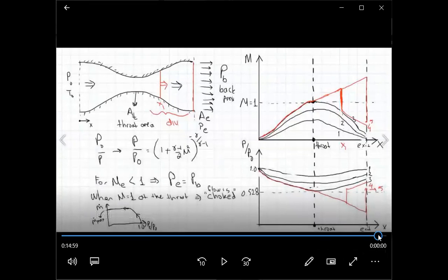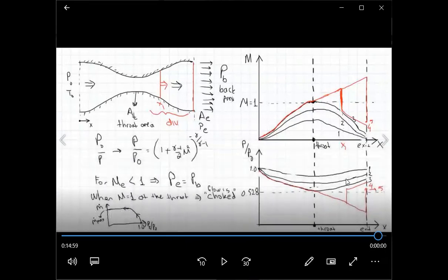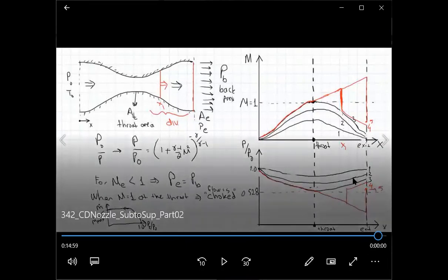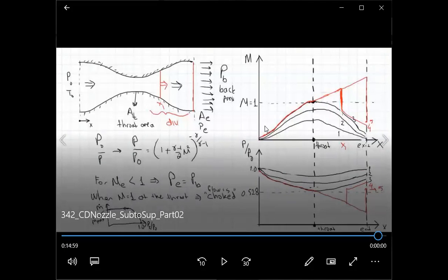But as you see, if we keep reducing, what we're trying to achieve, to summarize in this video, is the fully supersonic condition in the diverging part without any shock wave. Because when we do have shock waves, they cause stagnation pressure loss. And if this is an engine, as I said in the video, it causes thrust reduction, we don't want that. And in supersonic wind tunnels, just upstream of the test section and inside the test section, we want fully supersonic flow.